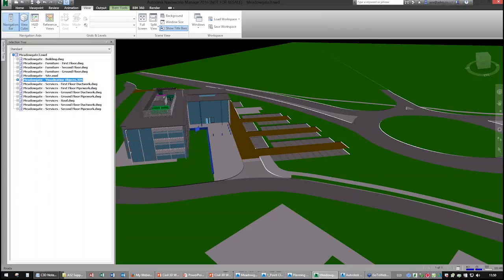But if I'm an engineer, I want to be able to see this. I want to be able to see this model, and that model is made up of 1, 2, 3, 4, 5, 6, 7, 8, 9, 10, 11 different drawings, potentially from different offices and different disciplines. I'd have to go and get all them models and put them into my, XREF them into my Civil 3D model separately. So then I end up being the manager. I'm managing all these models. And of course, when something's changed in the structural design, I want to be able to see that change. So if it's being managed in something like Navisworks, the best thing for me, rather than bringing in all these individuals into Civil 3D, is to bring this model in, the whole model in.